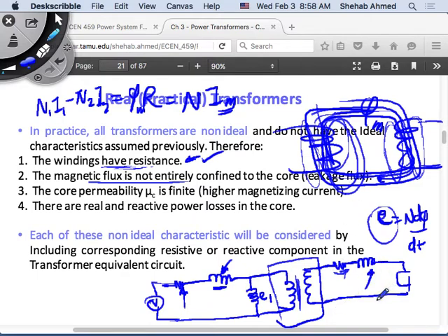Yes, sir. So I didn't understand why the E1 is before the transformer. It doesn't matter, you can put it here or here. What do you mean before the transformer? It's in parallel with the ideal transformer representation. Yeah, but the E1 is the value of the secondary, right? Equal to the voltage generated across the windings on the primary side. How about the voltage generated on the secondary side? We include that using the model of the ideal transformer, because this same flux is actually linking the secondary side and creating a voltage E2. And this E2 is related to E1 using N d phi by dt.